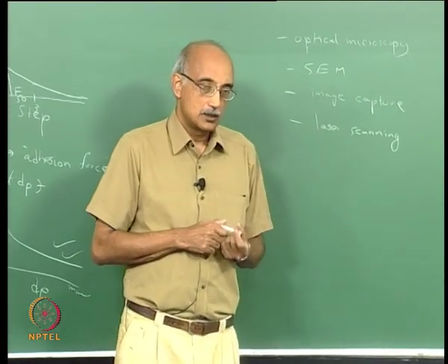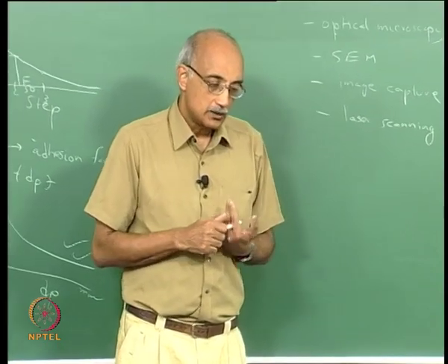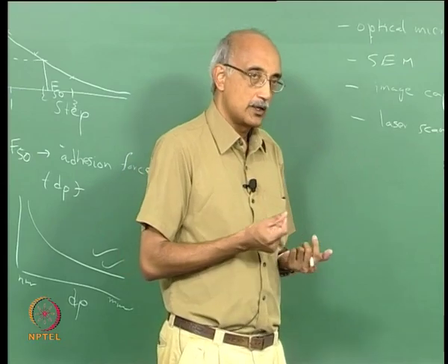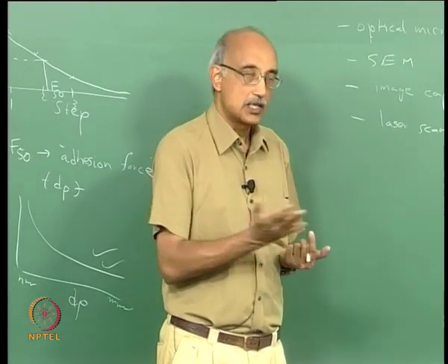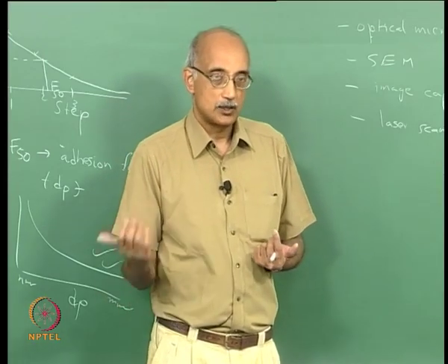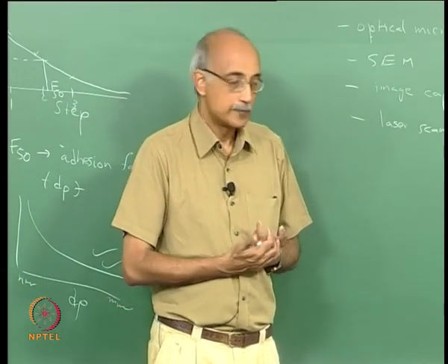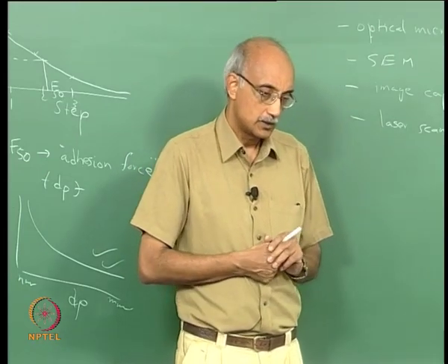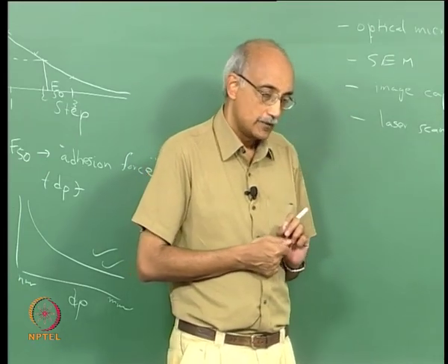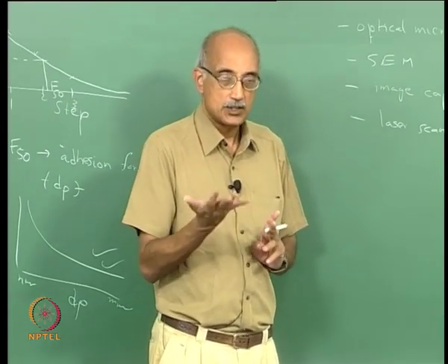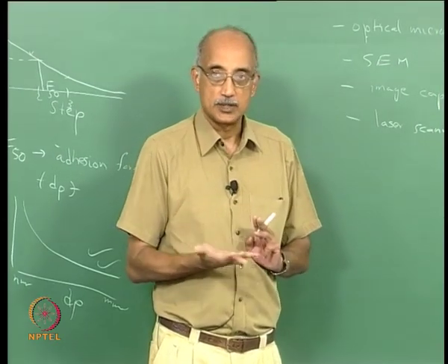Laser scanning, on the other hand, certainly improves the sensitivity and the resolution of the method, but it does require that you look at light scattering characteristics from a surface, again before and after application of the cleaning step. So laser scanning works well when you have a highly polished and smooth surface where the surface itself is not going to interfere with your measurements.